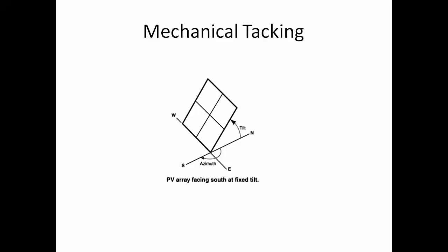Here, instead of changing the voltage or current, we are changing the mechanical angle of the panel towards the incoming solar flux, this incoming radiation from the sun. So it follows our sunflower, as the sunflower also tracks the sun continuously from day to evening. So this panel will also follow the same technique. Here we have two kinds of tracking, one dimensional or two dimensional tracking. A sunflower usually does two dimensional tracking.